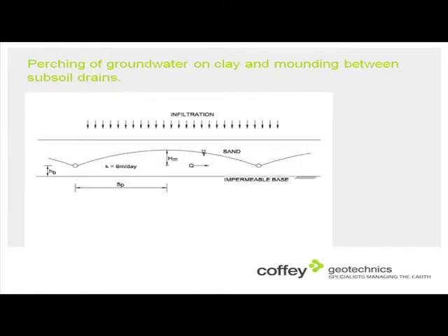Perching of groundwater on the clay and mounding between subsoil drains. We need to remember when we're looking at these things that the groundwater level is not the same as the depth of the subsoil drains. If we put subsoil drains in, there'll be mounding in between.